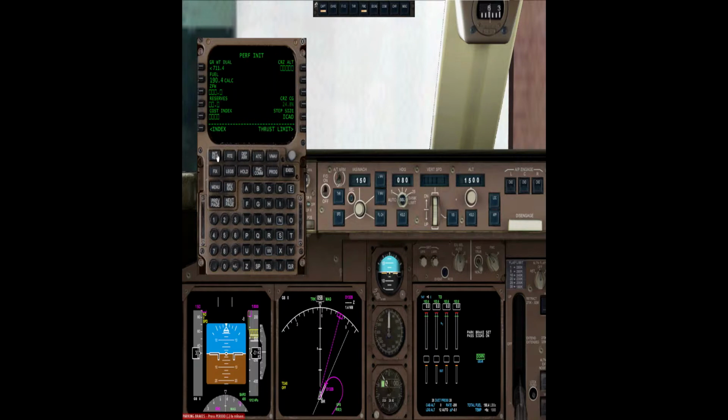Next thing is we make sure our fuel is all done right. What have we got there? 190,000 pounds of fuel, that's what I'd need. So that will be our gross weight, so we click that, puts it in. I normally put in reserves of 20,000 pounds, it's normally more than that. Cost index, I believe going west is 90. Virgin, and our initial cruise flight level is flight level 340, 34,000 feet.